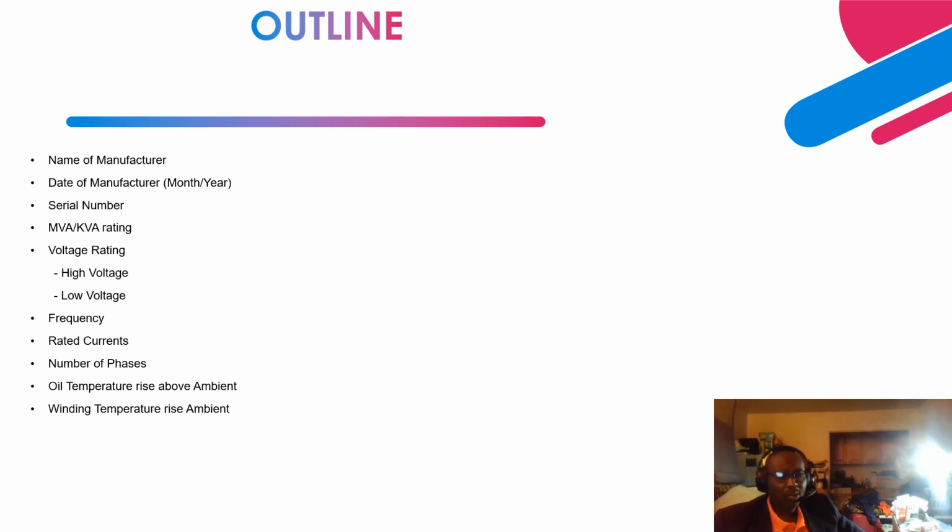On the other hand, you can have a generator step-up transformer that steps up the voltage from a lower voltage to a higher voltage. These are typical examples of transformers that are integrated to generators. They step the voltage up from 13.8 kV or 18 kV.